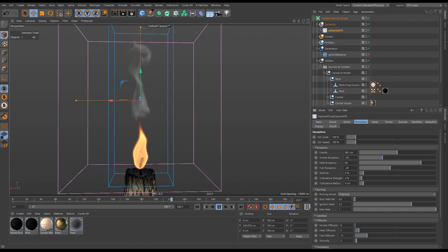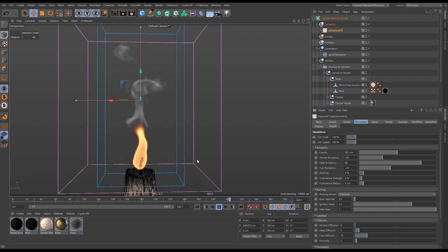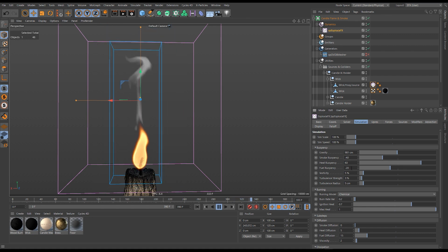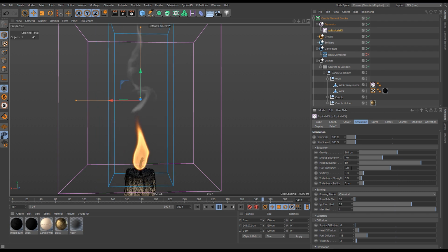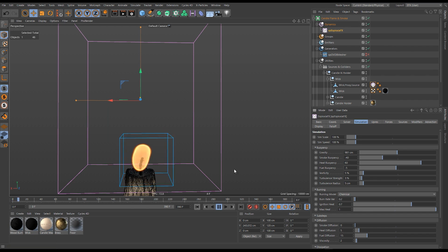The other one there is the fuel. If you look at the bottom of our flame here, you'll see it sagging occasionally. What's happening there is the unburnt fuel obviously has not much temperature around here, not much heat, and therefore it sags and drops down. I want the fuel to behave as though it's vaporized paraffin, and therefore it's much closer to the density of air, so it would be pretty neutrally buoyant. I'm going to make it slightly negative, just -5. And that's calmed down that sagging at the bottom there, and it's looking much nicer.